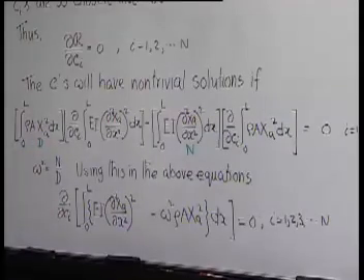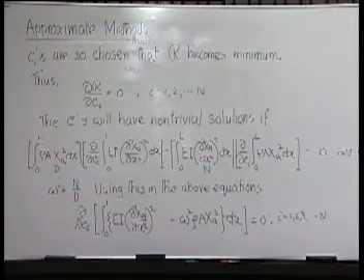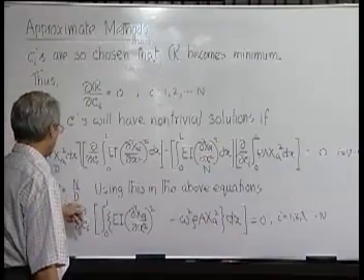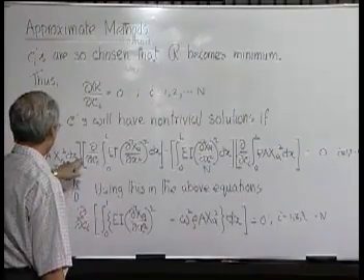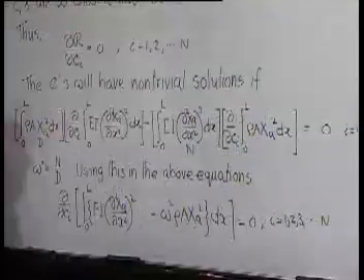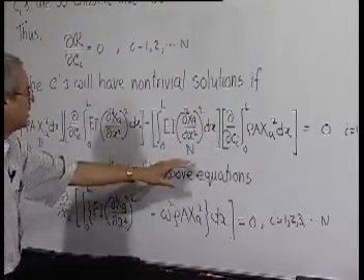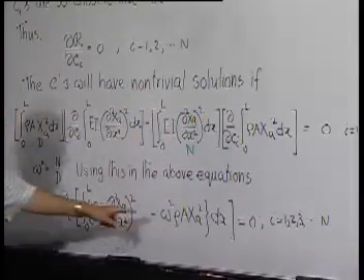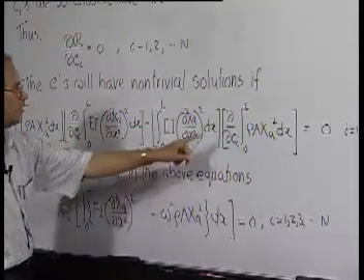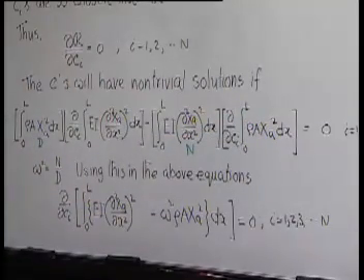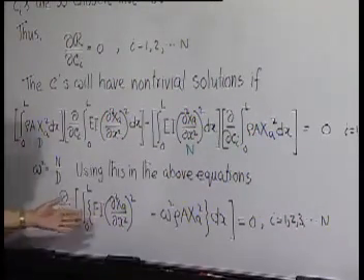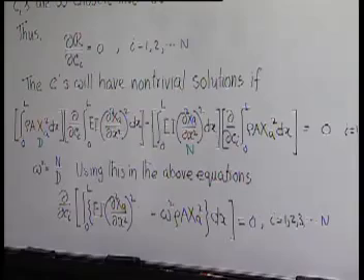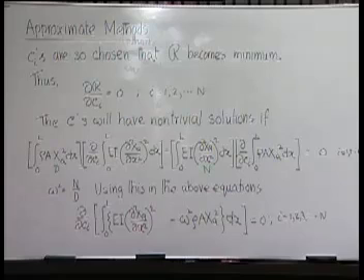so there will be now n such equations. It is very easy to see if we use this, so we can always take this common and take out this. The moment we take out this, it goes below here and this becomes omega square. So it becomes omega square and then this remains. So it is straightforward. Then these n equations in Ci, C1, C2, C3 up to Cn, are homogeneous equations and can have a solution only when the determinant becomes 0.